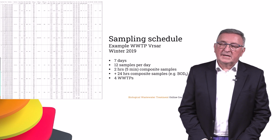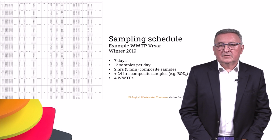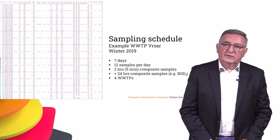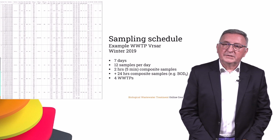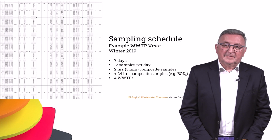We collected 12 samples per day. These samples were 2-hour, 5-minute composite samples. A 2-hour composite sample means that we had 12 samples per day, and each of these samples is collected every 5 minutes, so we needed 12 small samples per hour, which means 24 small samples per 2 hours. So a 2-hour composite sample had 24 small samples in it.